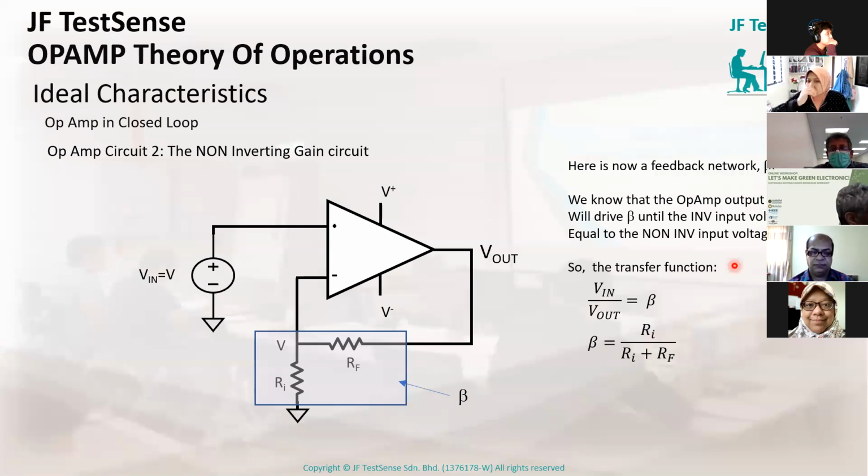You can see that a gain circuit is very easily realized by just choosing different values for the input resistance and the feedback resistance. This is a very typical circuit that can be used for gaining voltages on our test circuit.